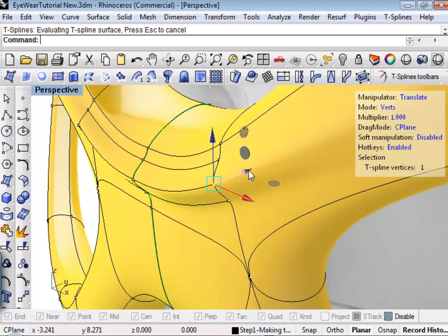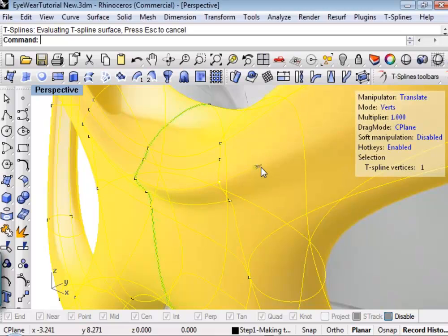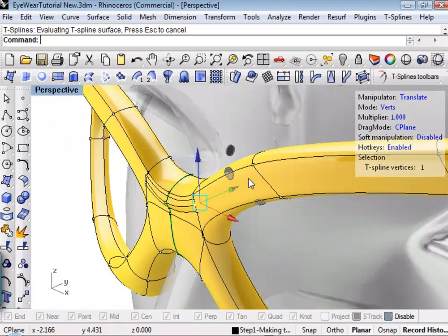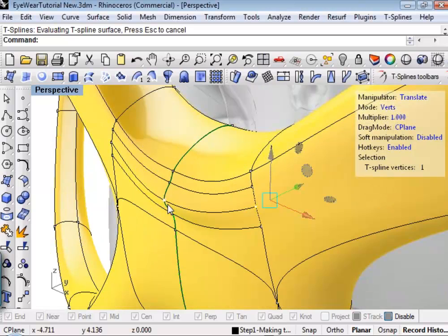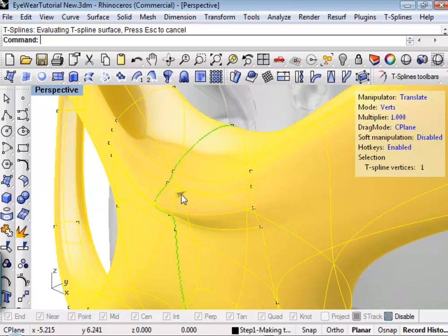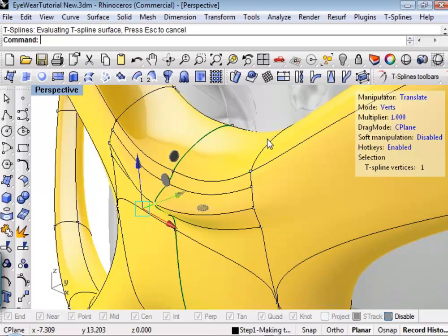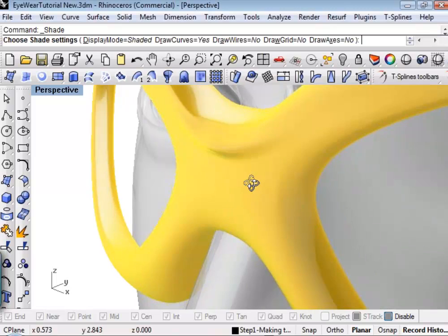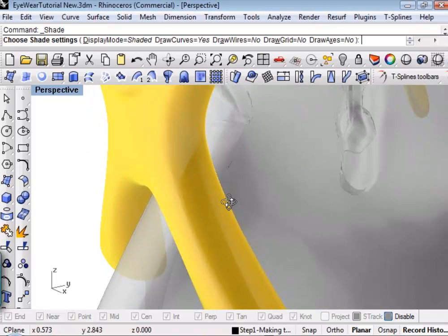I can pick this vert, and I can have it die out faster than a crease. So I can really isolate that detail, whereas a crease has to have two faces. This I can isolate to be just where I want. So depending on the effect you want, that's the difference between if you wanted to use a crease versus inserting an edge.